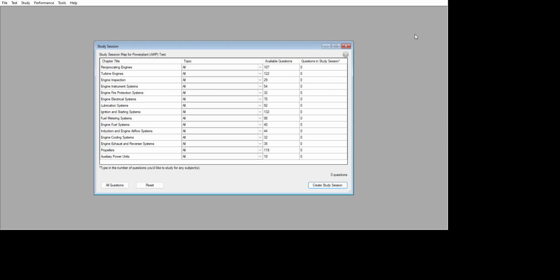Oil level and magnetic drain plug condition. What likely effect would a cracked distributor rotor have on a magneto? Ground the secondary circuit through the crack.